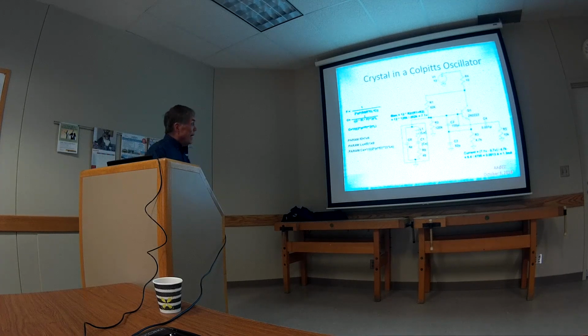Now, we're going to put parameters in like that. I'll show you how we do this, but this is how LTspice is going to pick up those parameters. You see, instead of a fixed value for the inductance, I'm going to put an LS, a series inductance, and I put it in brackets. Brackets tell LTspice that it's looking for a formula. Where is LTspice going to look? It's going to look over here.